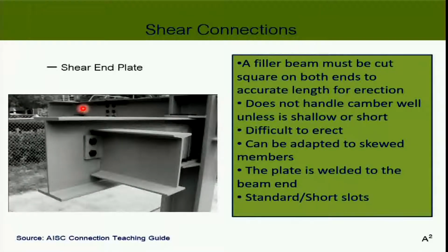It looks like that. Okay? The plate is at the end of the beam. The plate should be welded to the beam from the fabrication shop, and then brought to the site, and then you bolt the beam with the support. Should be simple, but look at the details. If the fabrication is not good, the length of the beam is not accurate, we're going to have a big problem, right? So that means the fabrication process has to be very, very good.